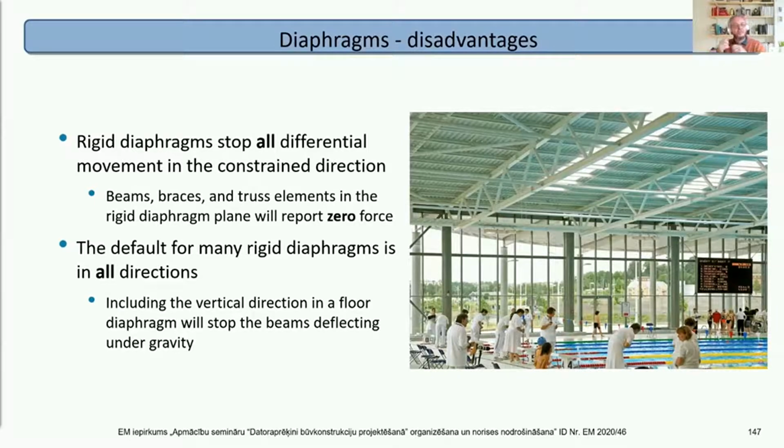Also, default for rigid diaphragms is rigid in all 3 or 6 directions. You want to make sure that does not happen. In plane stiffness only, out of plane flexible. Otherwise, you'll get no deflection under gravity.